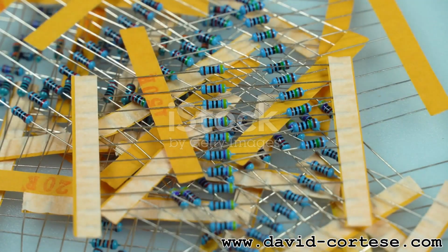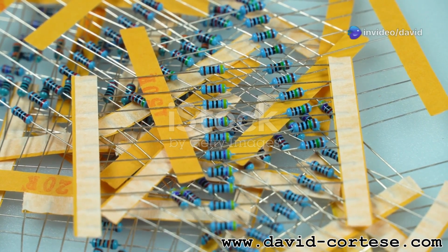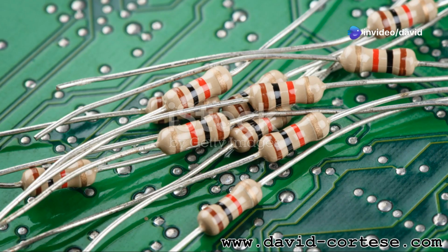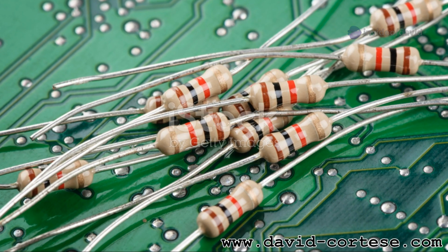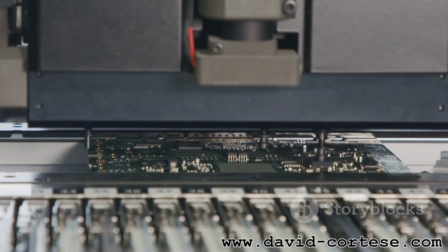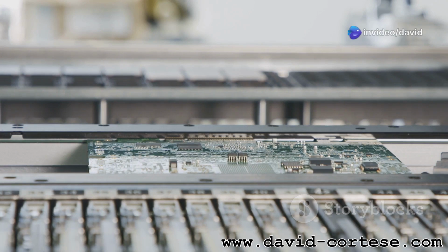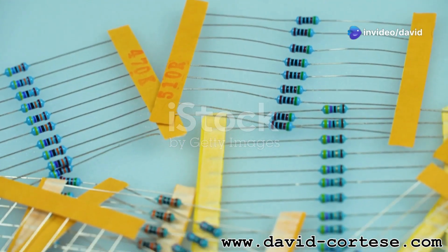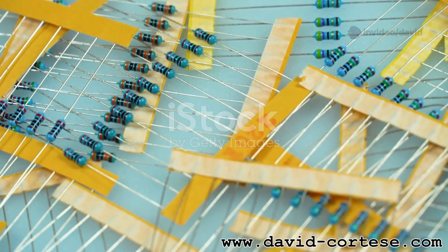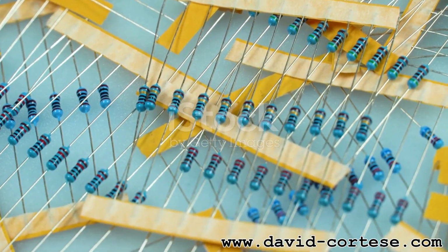Resistors come in a dazzling array of shapes, sizes, and materials, each tailored to specific applications and power requirements. Some common types of resistors include carbon composition resistors. These are among the most common and inexpensive types of resistors. They're made from a mixture of carbon particles and a binding material, molded into a cylindrical shape. Carbon composition resistors are suitable for general-purpose applications, but have a wider tolerance range, meaning their actual resistance can vary slightly from their stated value.